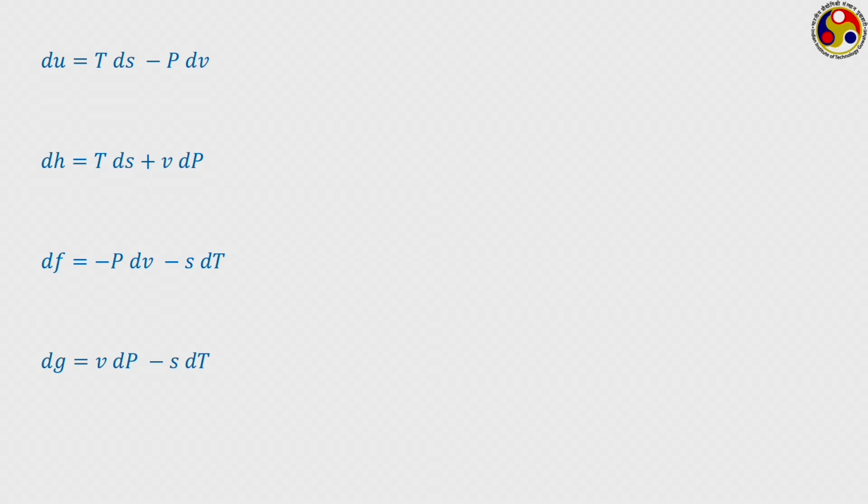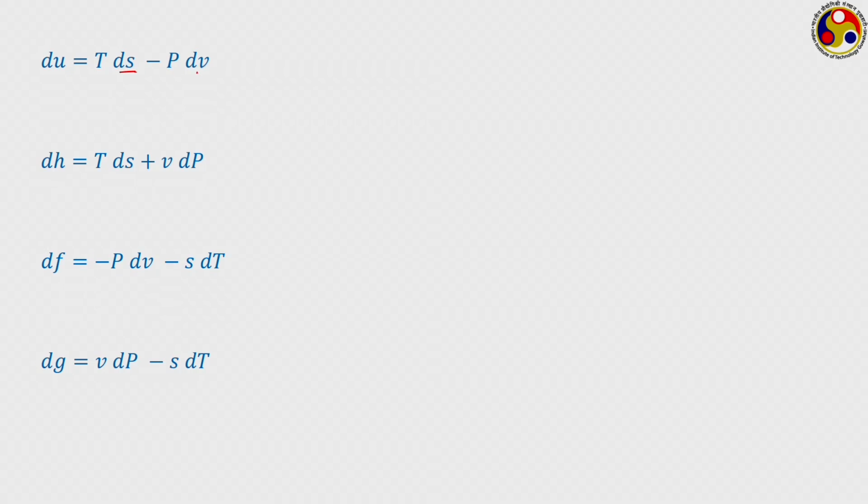Now, as internal energy is a property, then if this small s and small v are independent intensive properties, they are intensive, of course, they are written in intensive sense, and if they are independent of each other, then we can use the previous principle. So, I am rewriting that dz equal to m dx plus n dy, and if z has to be a property, we know that the principle is ∂m/∂y at x should be equal to ∂n/∂x at y.